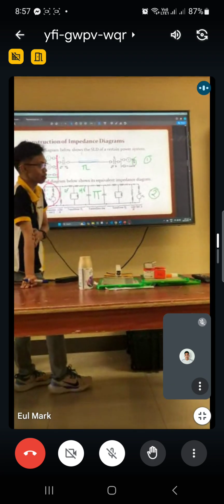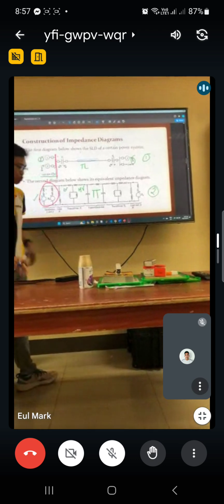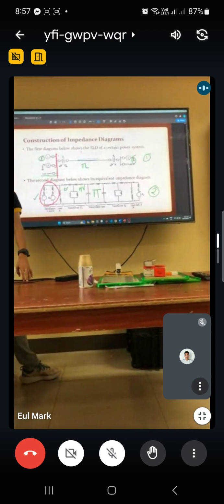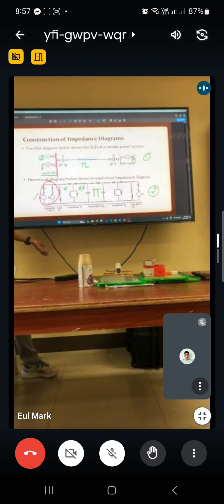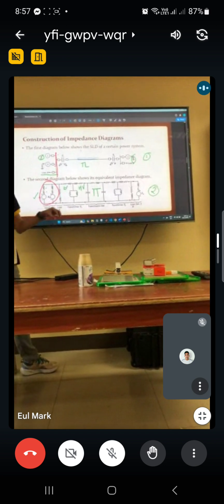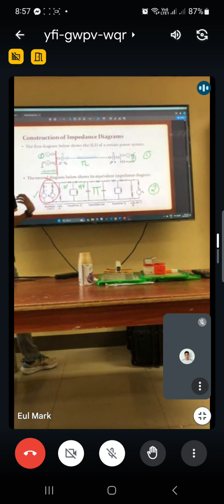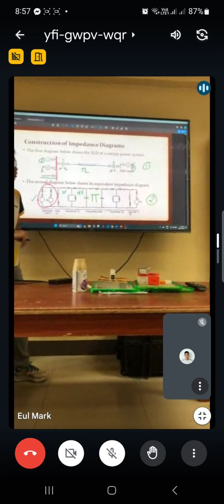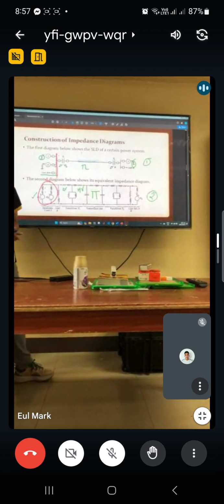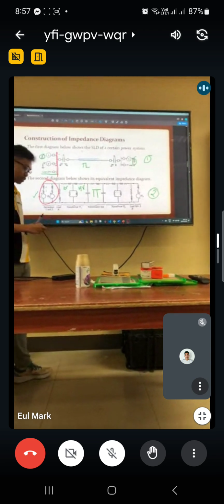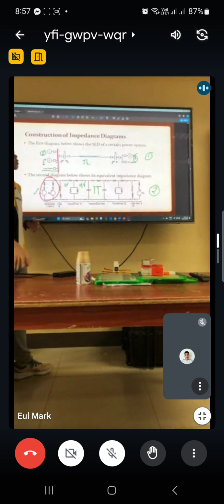It doesn't make sense otherwise, right? Connecting transformer 1 directly to transformer 2, for the sake of what? Step down, step up, then step down. In a power system, especially for power delivery, you connect them with a transmission line. We cannot connect the transformers by themselves to deliver power.